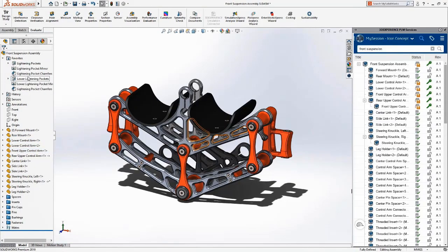So rather than spend the next 5 minutes doing some sketching and modeling work in SolidWorks, we'll just fast forward 5 or 10 minutes or so, and Don's gone ahead and added those cutouts to the suspension component. So he's got a couple of options here. He could save it in SolidWorks and just save it locally, because when he's opened this up from the 3DEXPERIENCE platform, it's downloaded it to his local working area on his workstation, which keeps a live connection to the platform. Now, if he was going to go out and visit a supplier and didn't have an internet connection but still needed to access that data, he can still open it up in SolidWorks from his local working area on his hard drive.